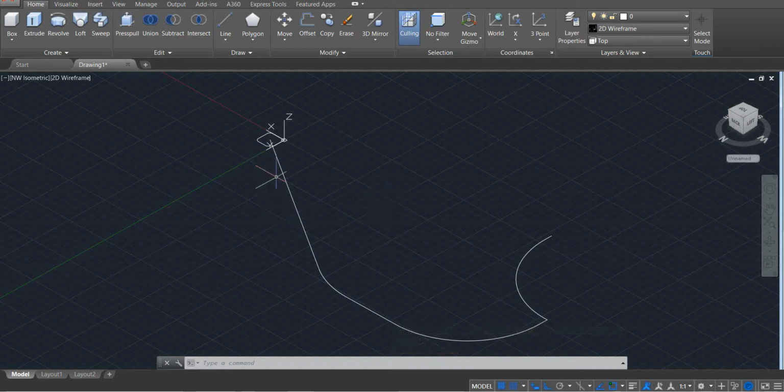It means that to extend it, it should be projected out of the section. They shouldn't be in the same plane. So the question is how we can draw multiple sketches over multiple sections or multiple planes. We do have here the XY plane, this is the sketch, and we have other planes like XZ and YZ. So for example, to be extruded, we should have this sketch already drawn in the XZ plane or in the YZ plane, so this cross section would follow it.